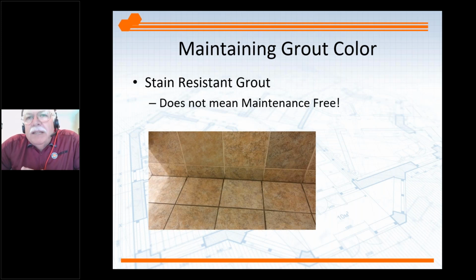And this is where, if you want to save a little bit of money, you can use your epoxy grouts or your single component grout on the floor and then go to a cement-based grout on the wall. Save your clients a little bit of money on those installations.